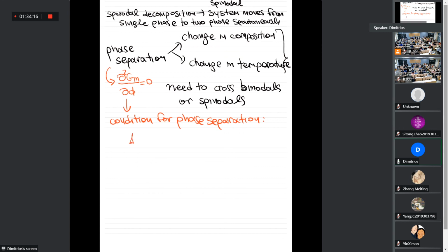So we end up with an equation that looks like that. Okay, but we already know that chi is given by alpha plus beta over temperature. So if we know these two, we can construct a theoretical spinodal curve, and that is how we are able to predict the phase behavior of a polymer blend.